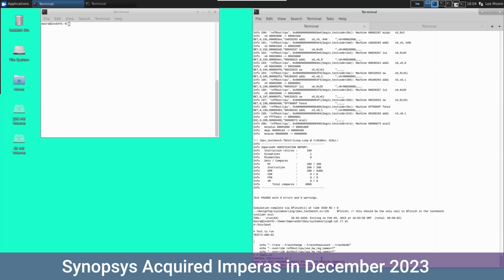So just to clarify and recap: we have a rich API in order to control and inform ImperasDV, and we use that by communicating data across the RVVI interface. On top of this, we have a set of comparison checks which tell us whenever there's a difference between the RTL and the ImperasDV environment. And when we have those, we can perform additional tracing and interactive interrogation to see why those differences occur. So we can quite quickly narrow down the problems and determine the correct resolution to why we're getting incorrect or non-intended behavior in the RTL versus our reference.